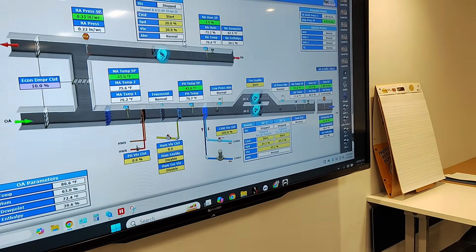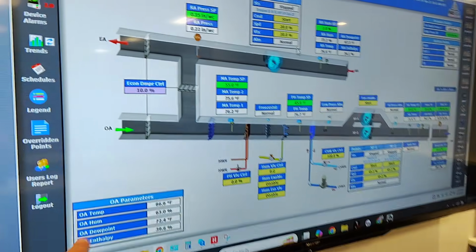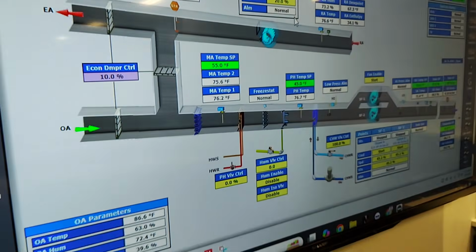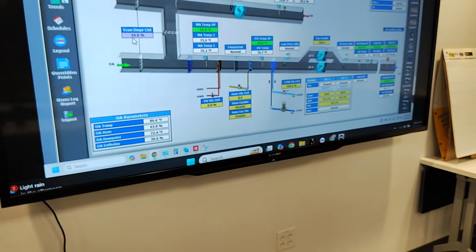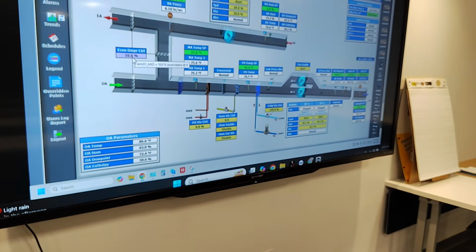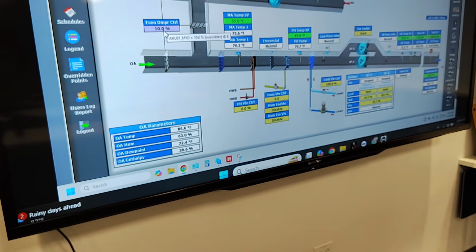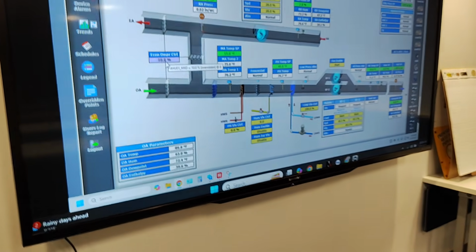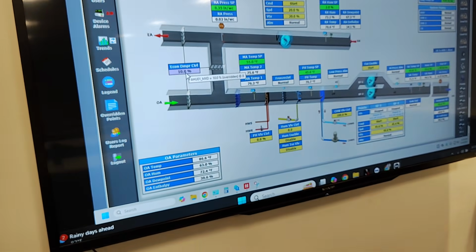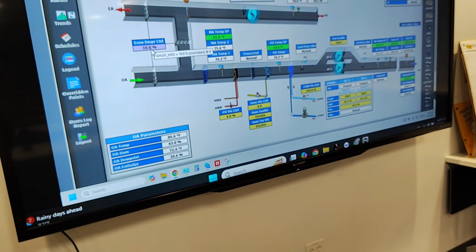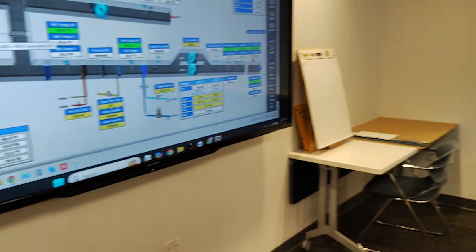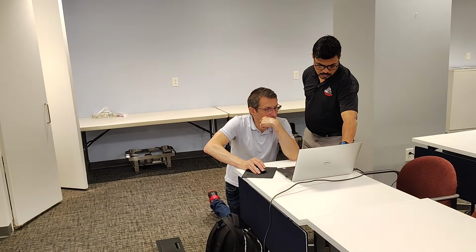And 90%. I'm sorry, the green, these are your set points. We have one here. Do a set. And the damper? Yeah, it's on 10% right now. It's the economizer damper, the damper for the outside air. So right now it's 10%. And what would be the automatic setting?